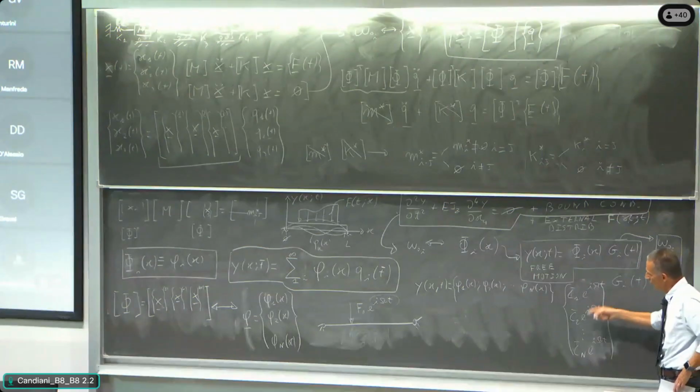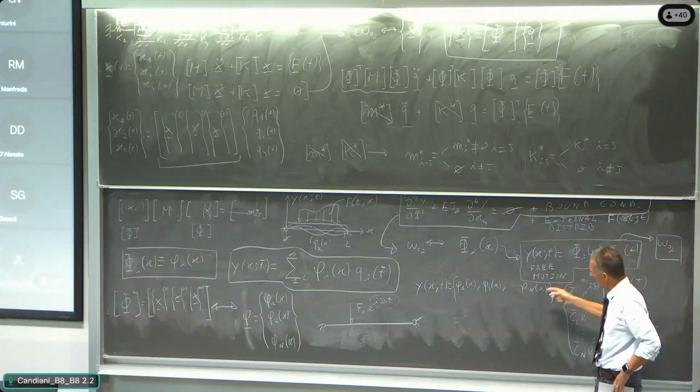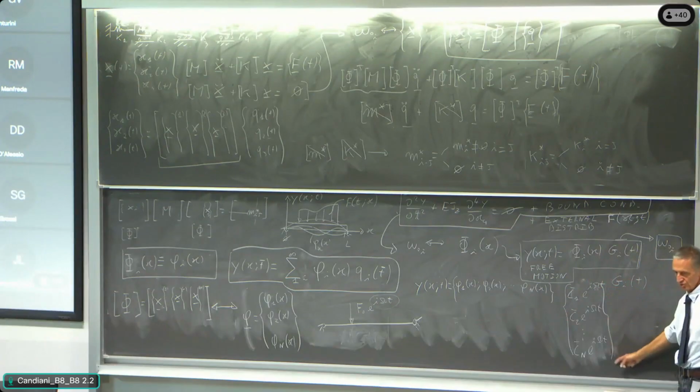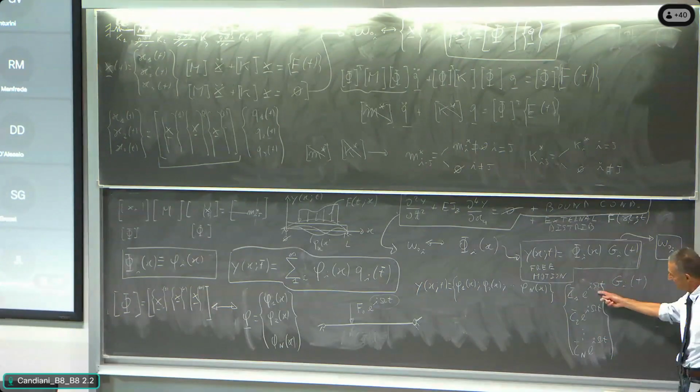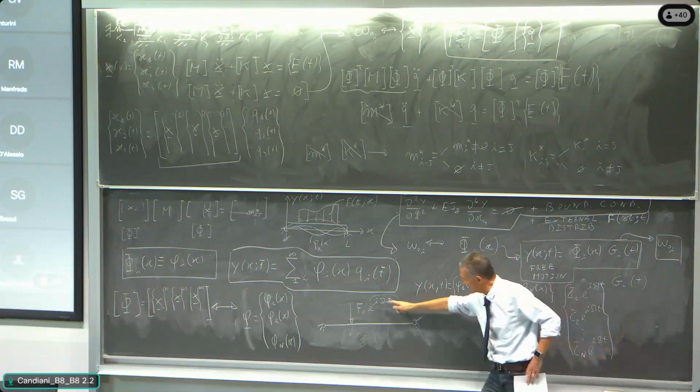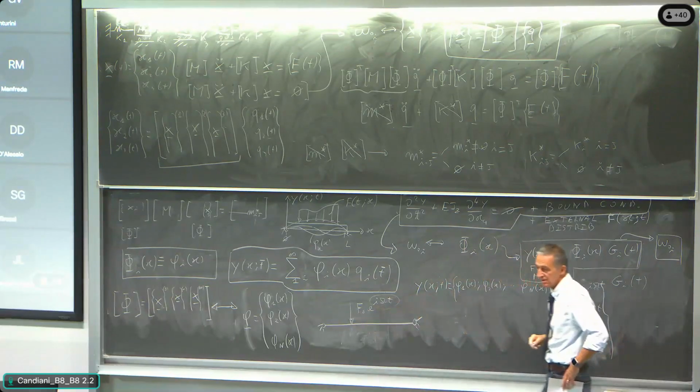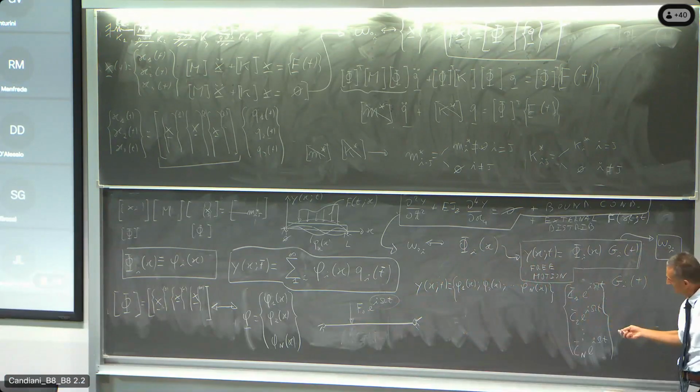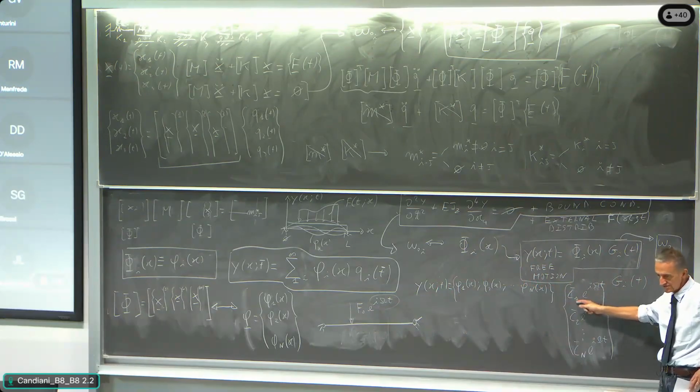So the Q1, Q2, Qn unknown that are defining the way in which the system is moving, they will be exactly the same function, the harmonic function running at the same frequency of the excitation, but multiplied by a constant that is different for each of them.